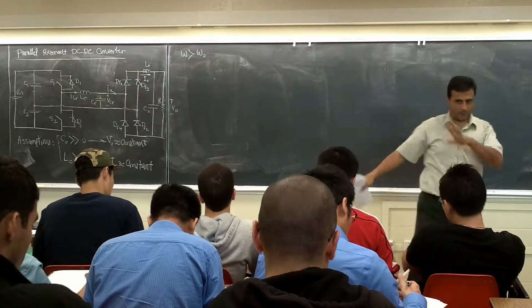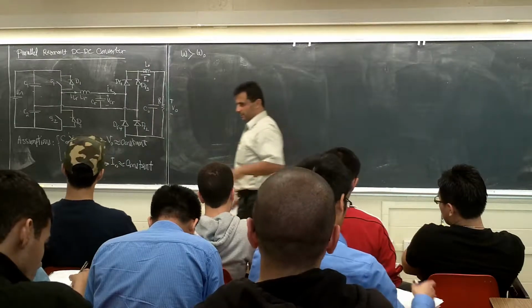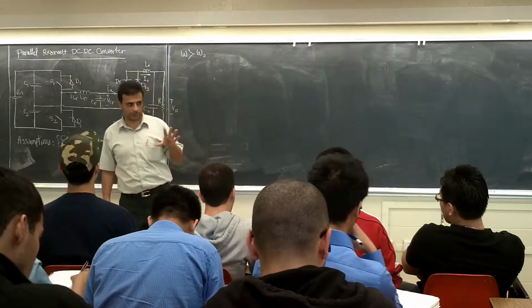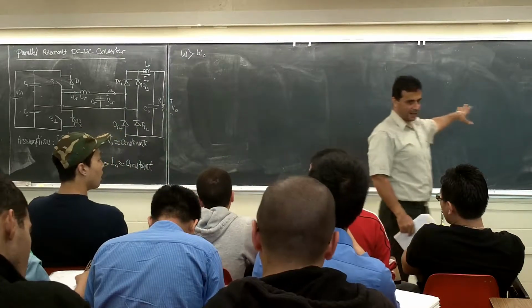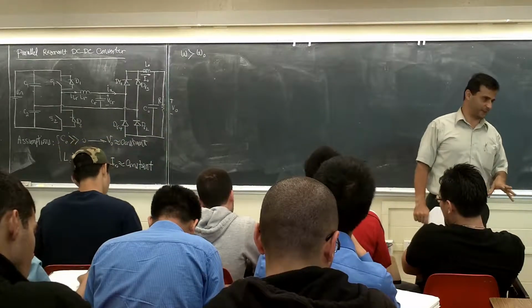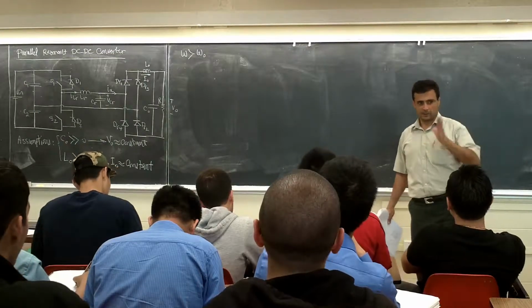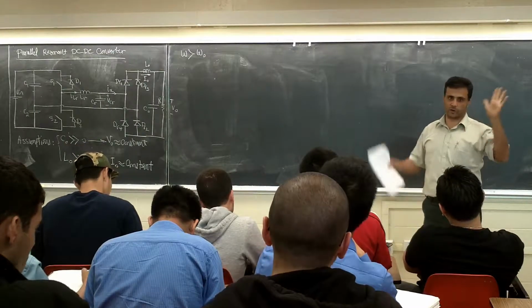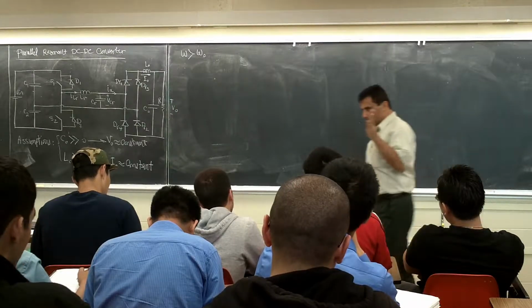Resonant frequency. This is what I'm talking about here. It is going to be for omega more than omega 0, which means the circuit is inductive, right? When omega is more than omega 0, XL is going to be more than XC, right? Because XC is 1 over C omega, right? At omega equal to omega 0, they are equal, right? They are going to cancel each other.